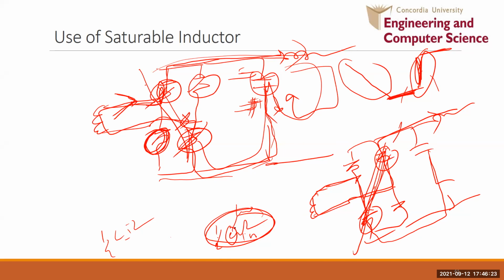Earlier we were discussing increasing the soft switching range by increasing L. Now we are discussing increasing the range by decreasing C, so that the energy storage is less. That is done through gallium nitride or silicon carbide devices because their capacitance is low.